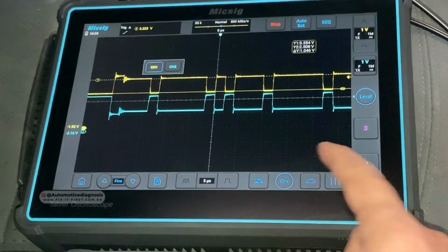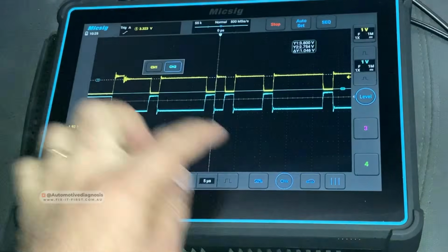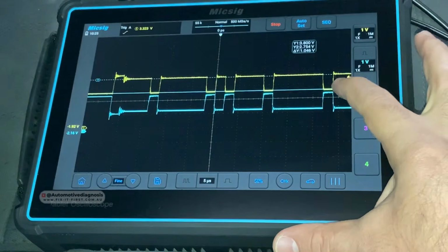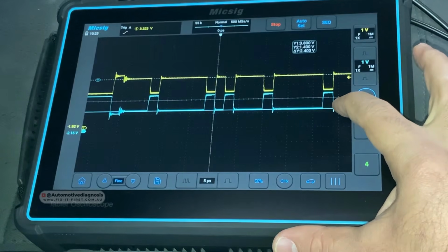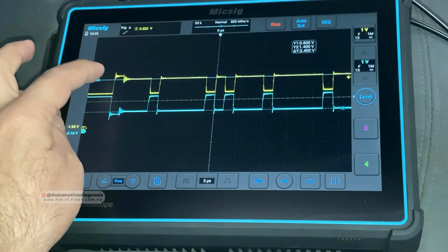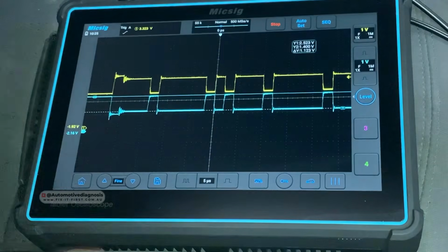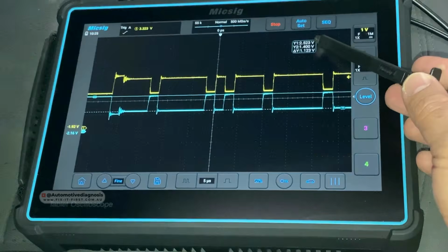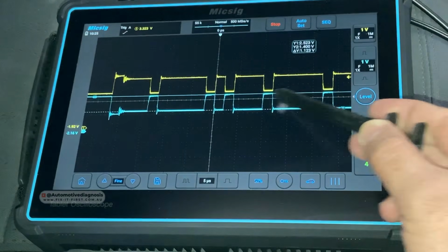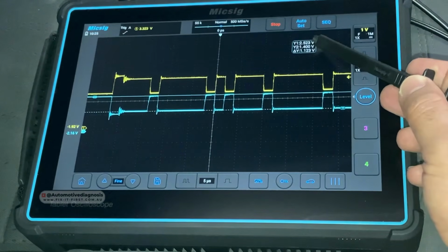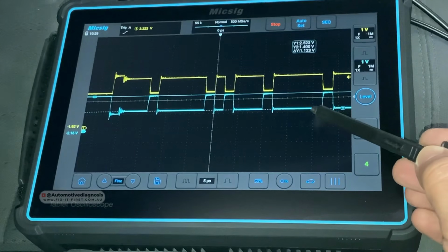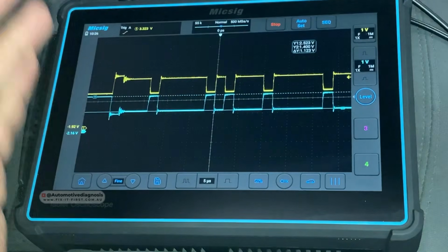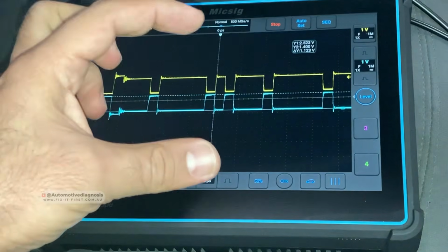And if you change the channel to channel 2, and if we do the same thing on channel 2, I'm gonna grab the cursor and this one right there. It's very responsive. I like how fast it works. So you see the Y1 in this case is the base voltage on the CAN low, it's 2.5, and the minimum voltage on CAN low is 1.4. So we need a nice symmetrical waveform with good voltage range.